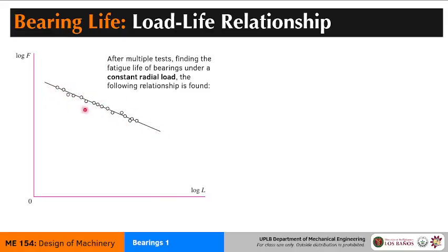In general, bearings tend to follow this kind of behavior. So this plot here is a log curve. I have a log relationship between the load, letter F here, and the life, which is letter L. The relationship comes out like this.